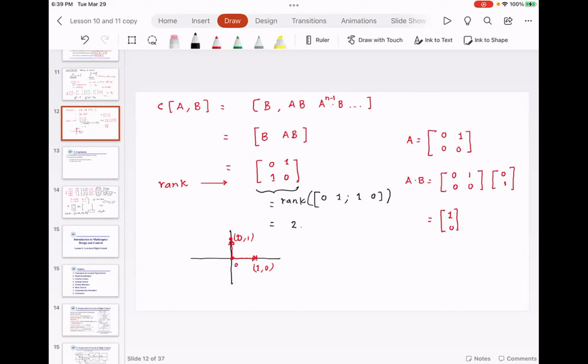Same thing happens when going towards the right. You pitch this a little bit or roll this a little bit. That way you induce a coupling between the external forcing function and the translational motion, and then it can go like that. When it is in level flight, no matter what you do, you cannot make this quadcopter go forward or sideways.